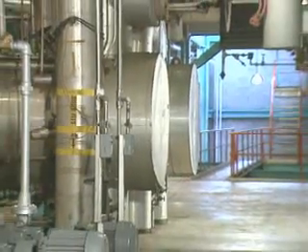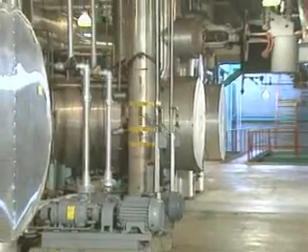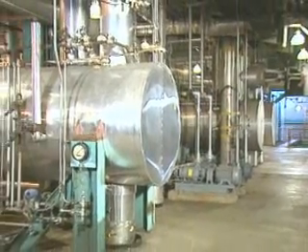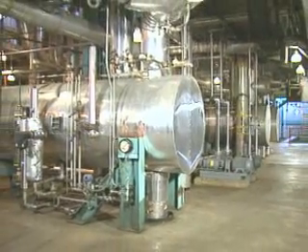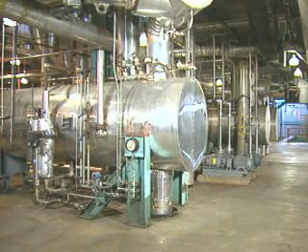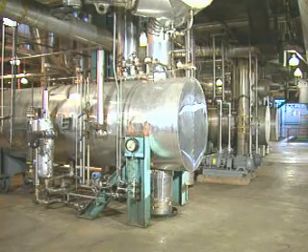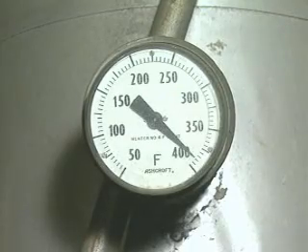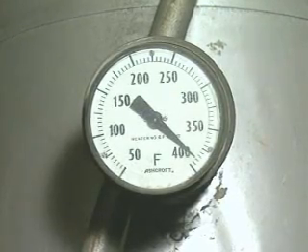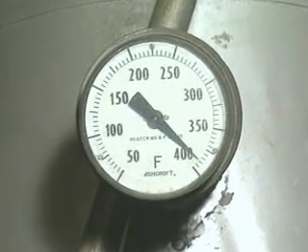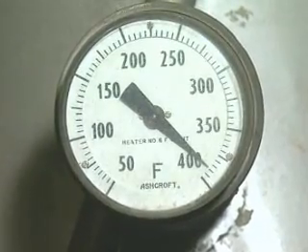Feedwater heaters in many condensate and feedwater systems are installed in trains or strings that are monitored as a unit during normal operation of the system. In this arrangement, the final feedwater outlet temperature is commonly used as one way to monitor the performance of the heaters. The final feedwater outlet temperature is the temperature of the feedwater coming out of the highest pressure feedwater heater on its way to the boiler's economizer.